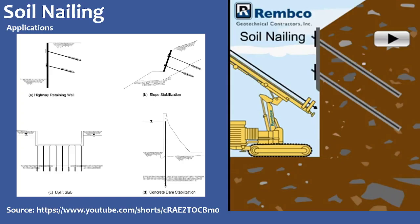So this week we have covered soil nailing. The principle of soil nailing is that whenever we have unstabilized ground or some excavation, and we want to prevent the ground from failing, we usually go for nailing or anchoring. The difference between nailing and anchoring is that nails are introduced directly into the ground, while anchoring has some grout material also. This week we will cover the nailing part.